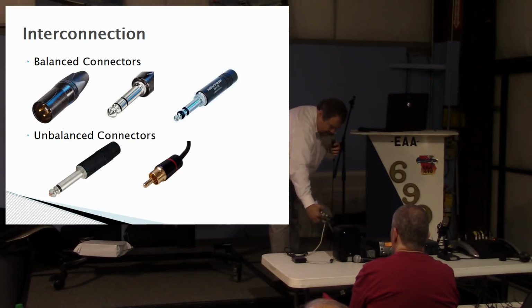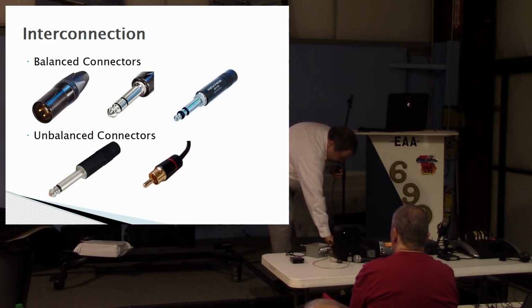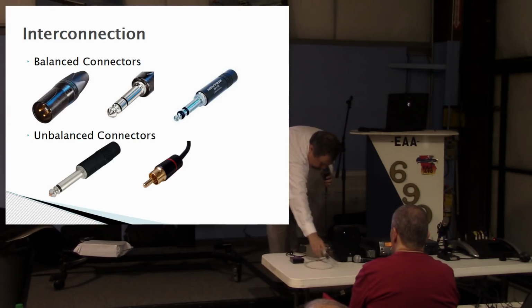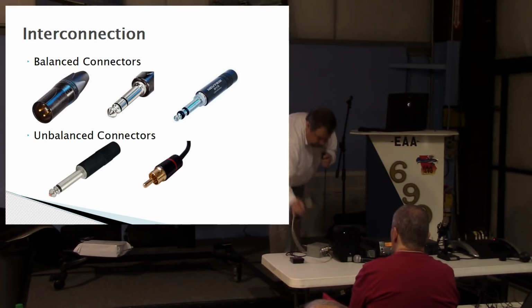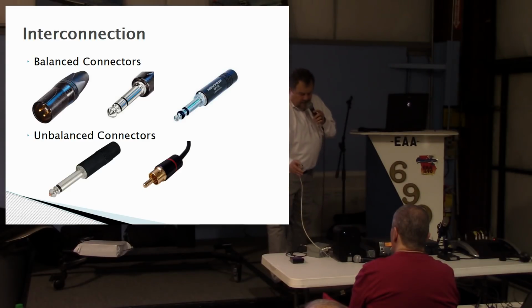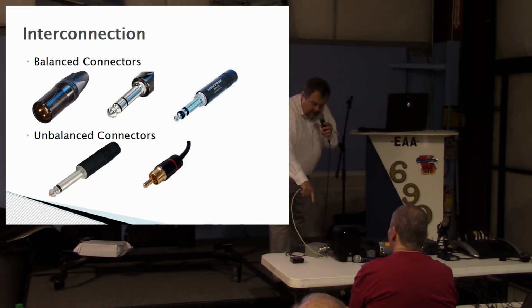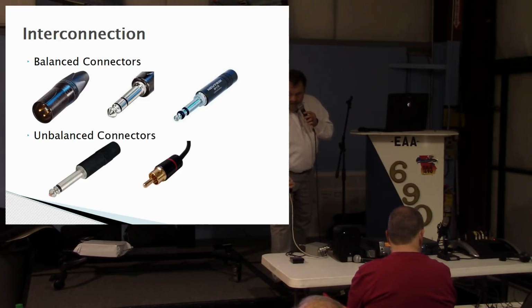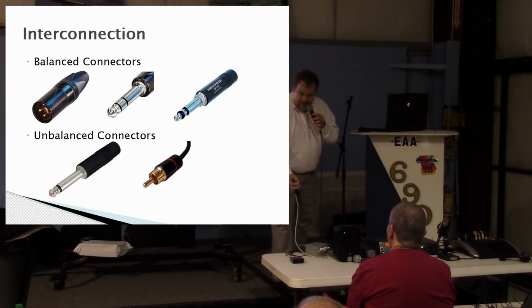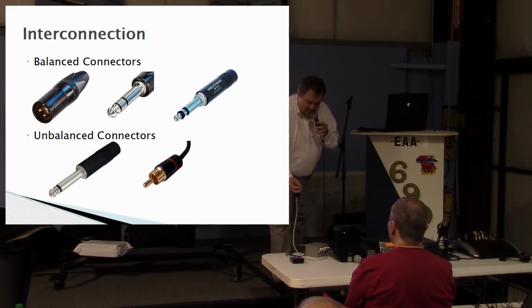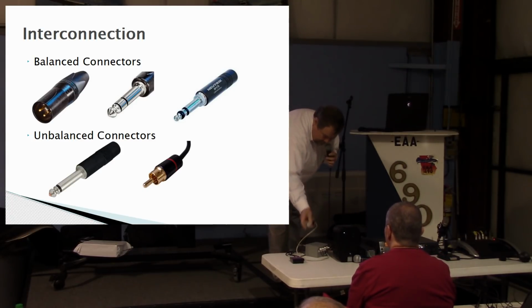Also in this box, I have a CW and RTTY interface, which is just a plain old serial interface. By keying DTR and CTS, it activates an optical isolator in the box, and it actually keys the rig. You have keys in either for RTTY, keys it for CW, or keys it for digital. 3 different signals that come in and are keyed through this port.